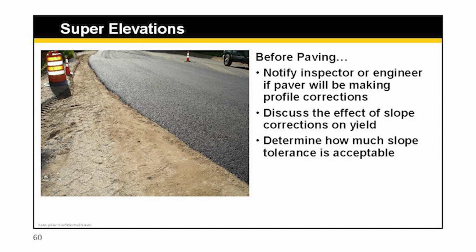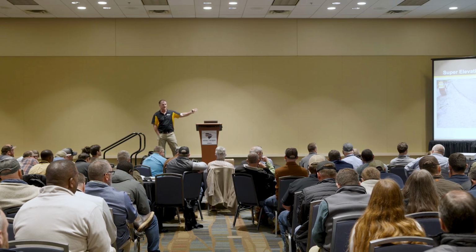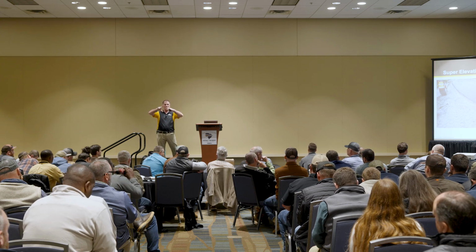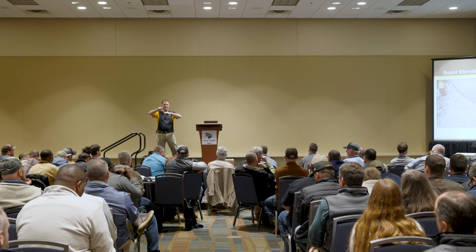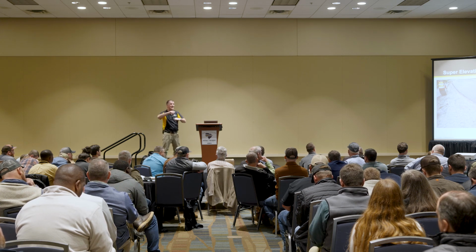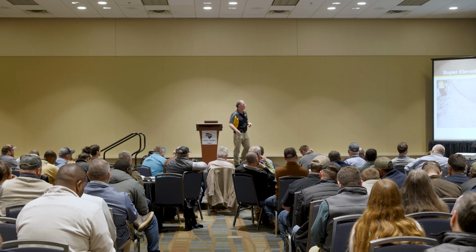And again, communication, right? Talking with the inspector, the owner. If you, as a contractor, see that, hey, I'm going to have to use a little more mix here to get this going through here at the 6%. Because what? I got slope out here, I got thickness. Again, if my base wasn't perfect, I'm going to be using more mix there. Or if it was too high, I'll be a little less. Doesn't seem like that happens too often.